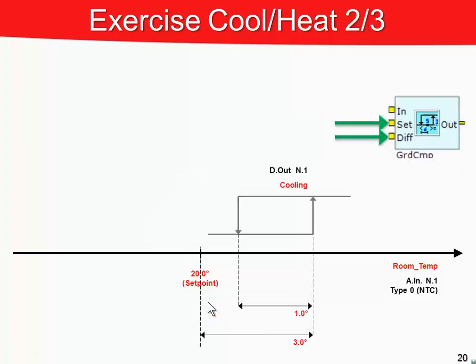While these are the specifications of the current exercise. There are three, and not two, operating parameters. The set point is available here too, but it is no longer in the center of the stage, it is on the left of the stage. The on and the off of the stage are relative values, defined by an offset of 3 degrees and a differential of 1 degree.